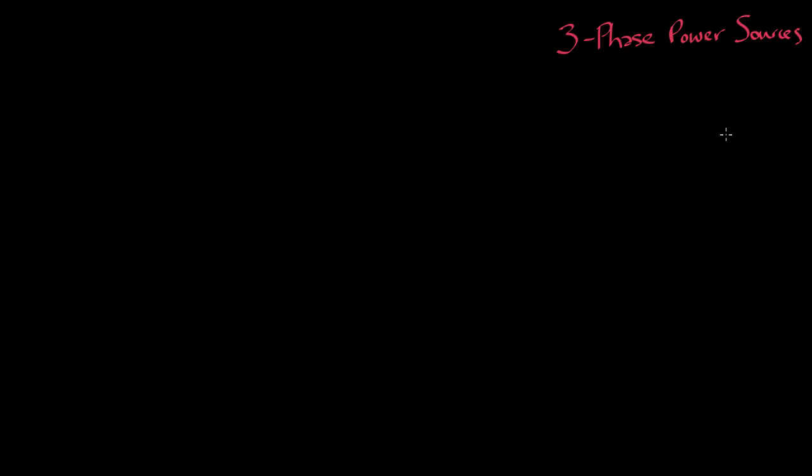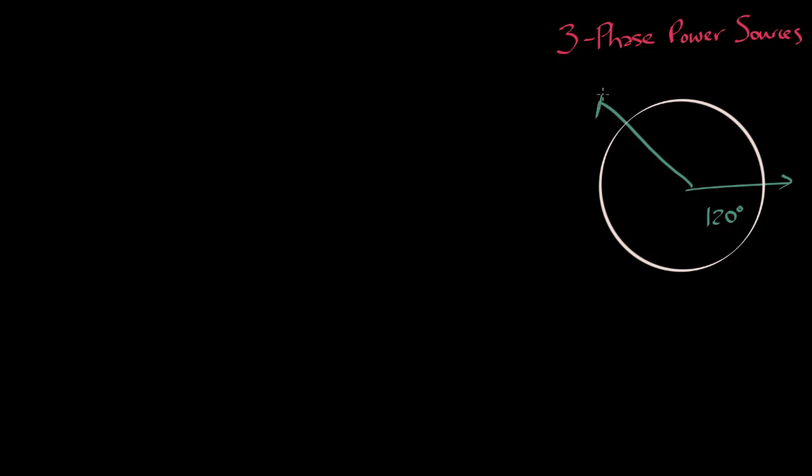Three-phase synchronous generators output 3 discrete waveforms that can be considered as 3 independent voltage sources. While being equal in magnitude and frequency, they are each offset from each other by 120 degrees. This ensures that they are evenly spaced through 360 degrees of rotation, that is, a full cycle. First A, then B, then C, at regular intervals.